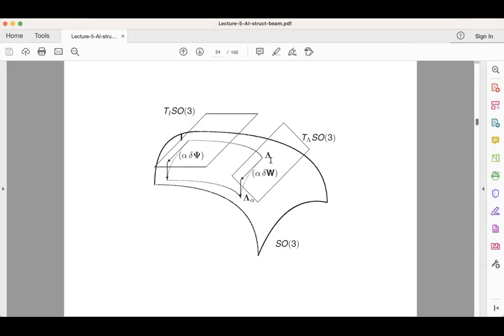Okay. And now in this cross section, the stresses are acting. So in solid mechanics, this would be a true Cauchy stress that sometimes you simply replace by the Kirchhoff stress, multiplying by J. We use that for plasticity, but they're still acting in the deformed configuration. Hence, they have been parameterized by using the coordinates from the initial configuration. You need this position vector, which takes you from the initial to the deformed configuration. And then here on beams, instead of just stress, either Cauchy or Kirchhoff, you actually need the stress resultants. And that's what I call N and M, okay?